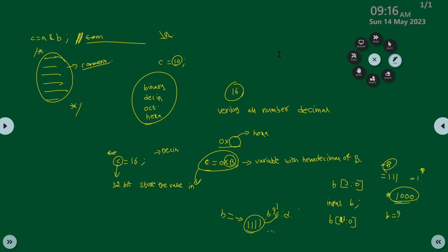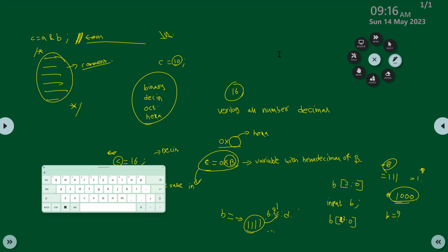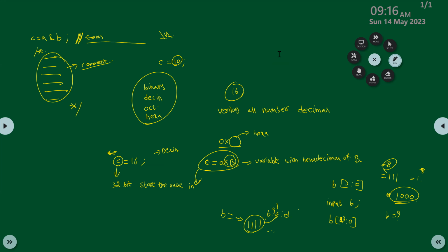Yes. Okay. So basically each time when we have A is equal to B question mark C colon D, the B has to be 1. In order to get A equal to C, B has to be 1, no matter what. For your question, the solution is the case statement. With this question mark approach, you cannot get the required operation. You have to use case statements on B. In case statements, you can write any values. So you can declare B as multiple inputs and write code for B equal to 8 in a case, something like that. I'll explain when we enter into the case statement explanation.